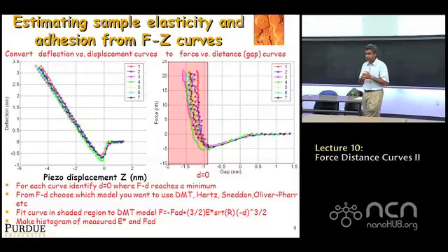And that has to do fundamentally with the fact that, in contact mechanics, the area of contact actually evolves. It's not like putting two flat plates and pressing them together. The amount of area of contact changes because it's sphere-plane contact, and that's why you get this 3/2 power law, even though the underlying constitutive properties of the elastic material are linear, but the geometry of contact introduces a nonlinearity in the process, okay?